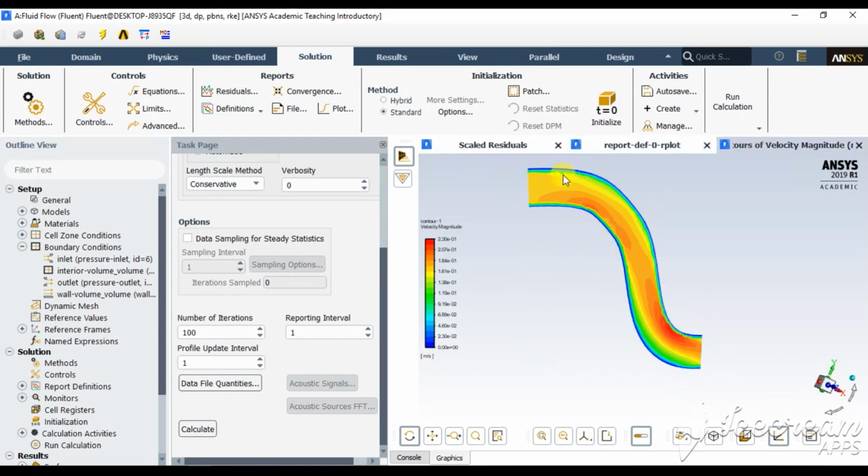So at the inlet, a 20 megapascal pressure inlet is there. The fluid is flowing from this direction. When the fluid is flowing, the boundary regions have a minimal velocity because there is friction, and at the center portion the velocity is very large. Because of this contouring region, there is a small decrement in dimension here. That's why. And you'll see all the velocity plots here, and we can also run an animation for that.